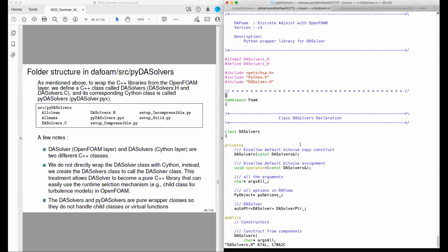Yeah, I got questions about computational cost for the forward and reverse mode AD. If you just differentiate OpenFOAM using operator overloading, for example, and you don't do any AD operation, just run the flow solver simulation again, this calculation becomes about 3 times slower. That's why we don't want to use the reverse AD mode to compute the flow, because that would be 3 times slower. For the forward mode AD, it's more or less the same, 3 times slower. That's assuming that you don't do any AD. But if you want to add some AD to compute the reverse mode AD, it will become even slower. In terms of memory, we haven't done a very comprehensive evaluation, but I will assume that you will use at least 2 or 3 times more memory than the original non-AD version of OpenFOAM. Hope that answers your questions.